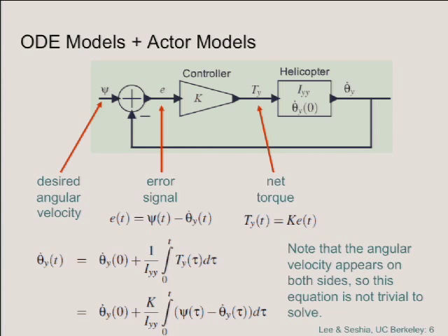And the reason it was dancing was that it was measuring its own motion using the accelerometer, and its own measurement of motion was confusing it about the tilt that it was seeing, and it was overreacting to that. And so, I could have tried to construct a joint differential equation model of the accelerometer and the robot dynamics and the motor dynamics, but it would have become very, very difficult rather quickly.